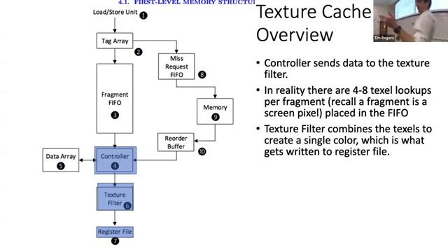These instructions are kind of crazy looking. They have many input operands. They're complex instructions because they're loading from texture places and trying to do this filtering as well. So it reads the data out and then sends it into this texture filter, which can blend together whatever output you're trying to write to. Okay, and that goes into the register file, right? The end result of a texture load blend operation is some color value that's stored in your register file that you'll probably then write out to memory with a different instruction.